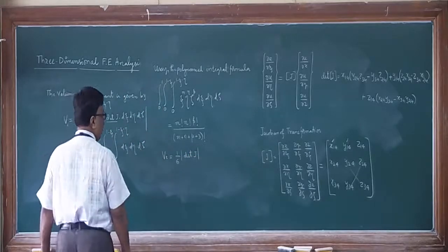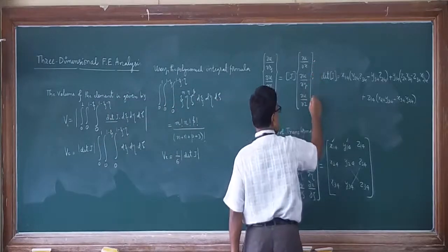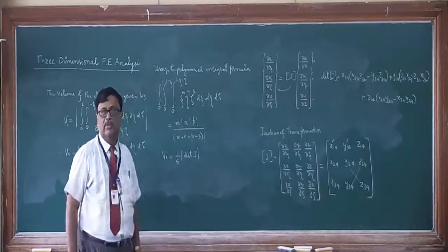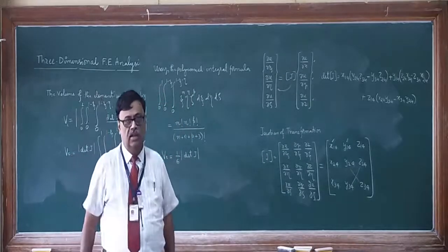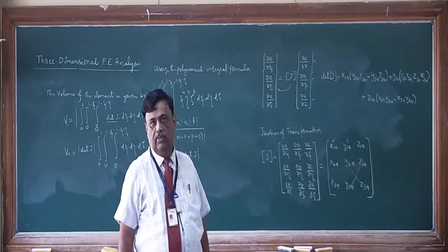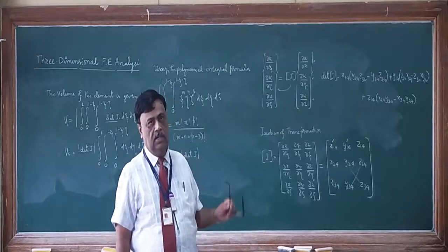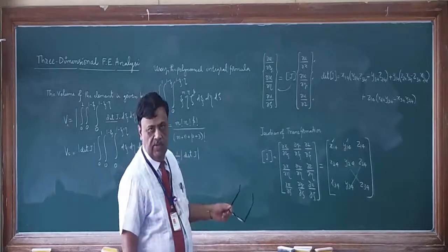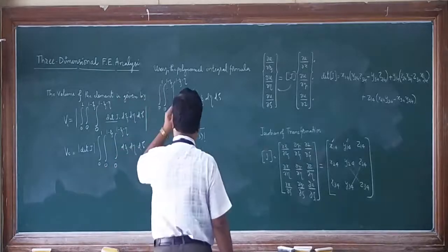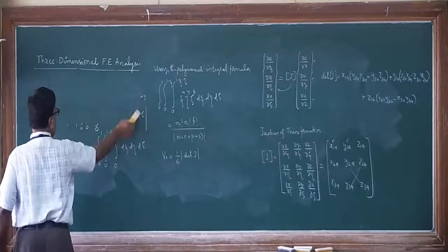So naturally, when we want this particular expression for finding the strain components, what we need is these. So obviously I have to take J this side and I have to take the inverse of the Jacobian matrix. As we did in our triangular elements, we have already taken the inverse of the Jacobian matrix, multiplied with all the zeta components, and then found the strain matrix, and before that the strain displacement matrix B, epsilon is equal to B Q, and we derived that. So now also here we will do similar analysis.